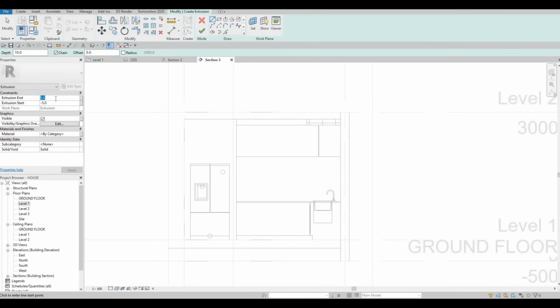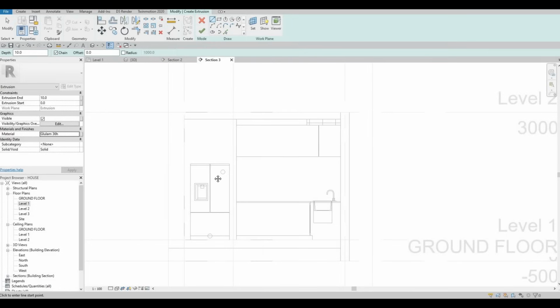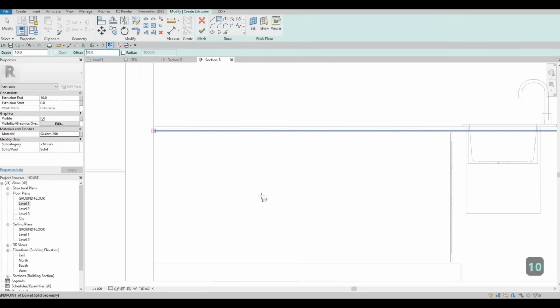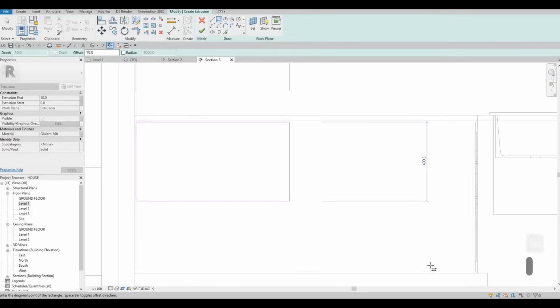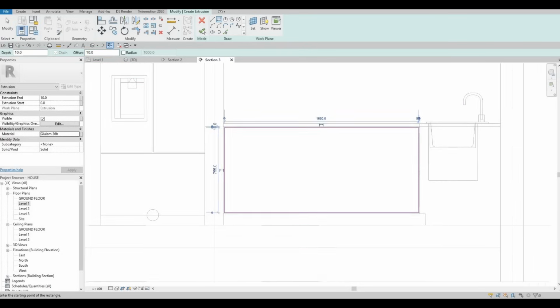So bottom first, and then here let's start at 0, and then luckily it's easy because we have the materials ready there. Here, select that, click on offset 10 first, and then let's add this one right here. There we go. And then click on finish,